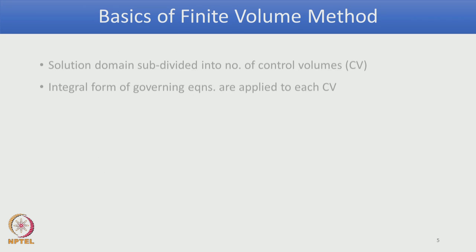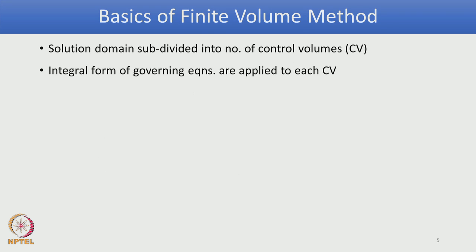So, in finite volume method we divide the domain into a number of control volumes. Then we learnt governing equations in 2 forms, one is the differential form, another is an integral form. So, in finite volume method we will mostly use the integral form of the governing equation, and this is applied to each control volume.